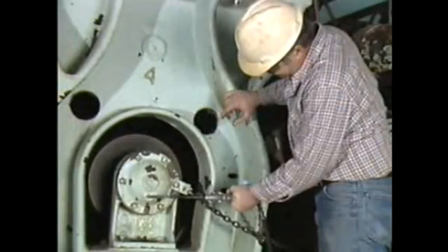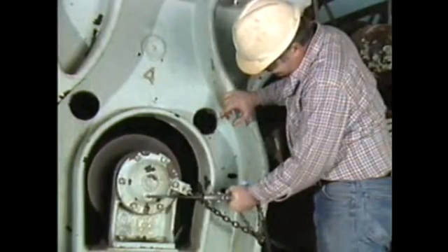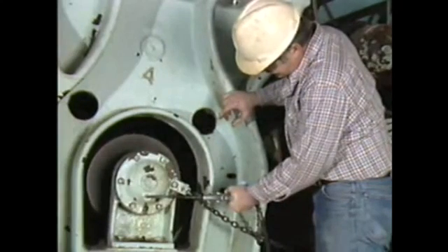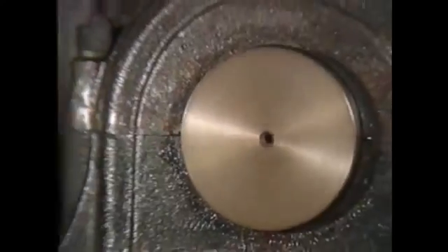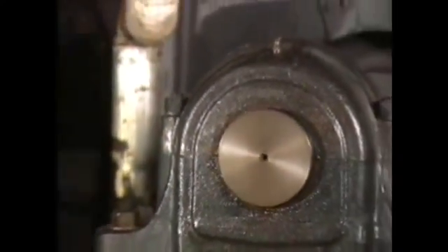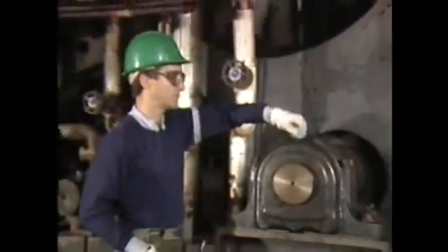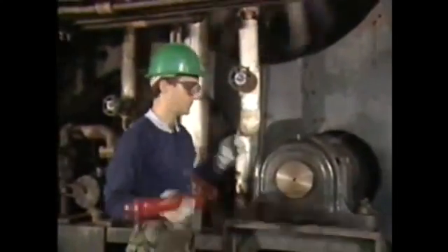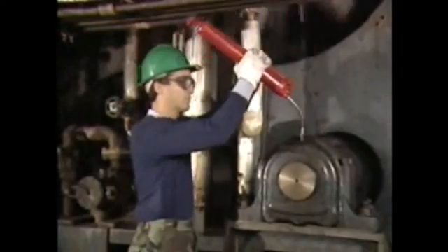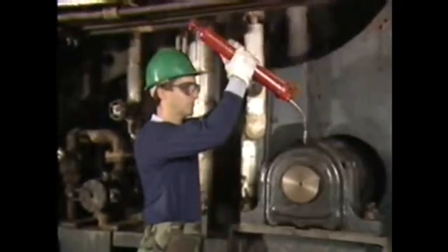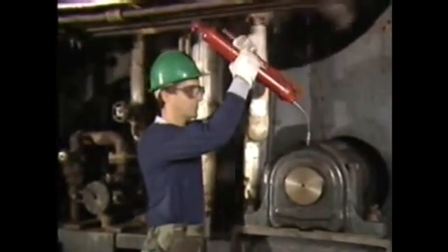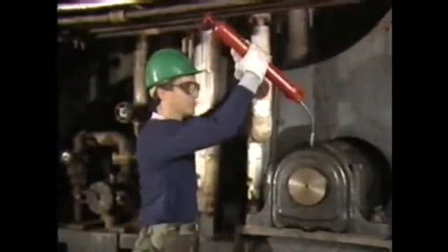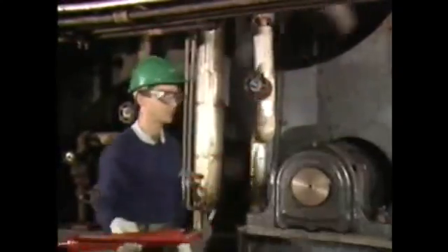Grease should be applied to the bearing while it is in motion to ensure that the grease will be evenly distributed. If the housing doesn't have a drain plug, the excess grease or old grease leaves the bearing through the shaft seals. In this case, it is very important to add grease slowly to the housing so that the shaft seals are not damaged. A good rule of thumb is to pump the grease gun no more than 2 or 3 times unless specific plant guidelines state otherwise.